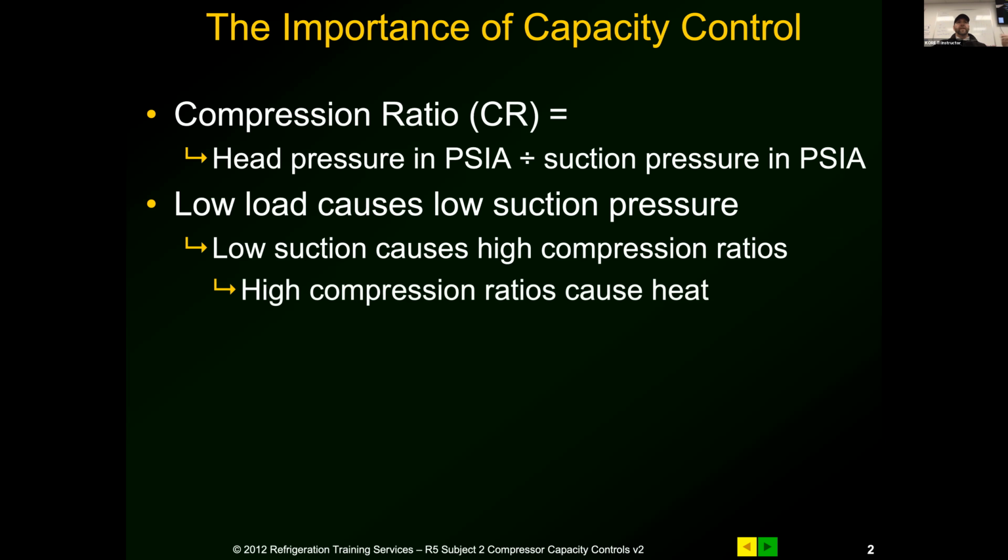Remember that refrigerant in vapor state, as it leaves the metering device and you get your pressure drop across your TXV, starts its absorption. It continues to absorb heat as it goes through the evaporator. That's what our superheat measurement is at the evaporator: we're seeing how much heat absorption is happening there. And then as it gets to the compressor, we're measuring it there as well because it's still happening. It happens all the way until it hits the condenser. That first bend of the condenser is when it starts to de-superheat, and then it starts to subcool.